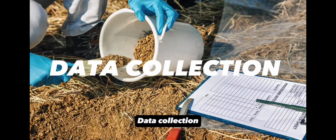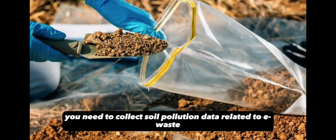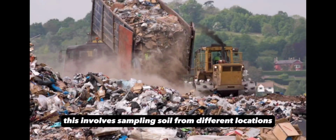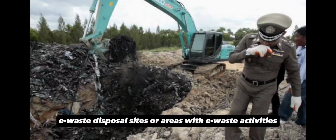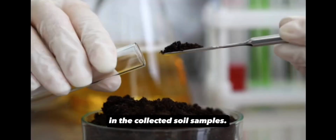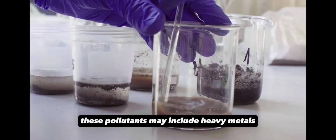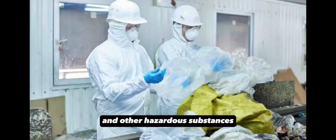Data collection. To apply kriging and inverse distance weighting, you need to collect soil pollution data related to e-waste. This involves sampling soil from different locations within and around disposal sites or areas with e-waste activities. Soil pollution measurement. Measure the concentration of pollutants in the collected soil samples. These pollutants may include heavy metals like lead, mercury, cadmium, etc., and other hazardous substances commonly found in e-waste.